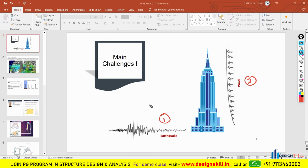These two forces have the same nature, but they have different behavior. Same nature means they are both lateral forces. Earthquake will create lateral forces in our building, and wind will also create lateral forces in our building. But the behavior of the forces is different. Earthquake will transfer the forces from bottom to top, and wind will transfer the forces from top to bottom.